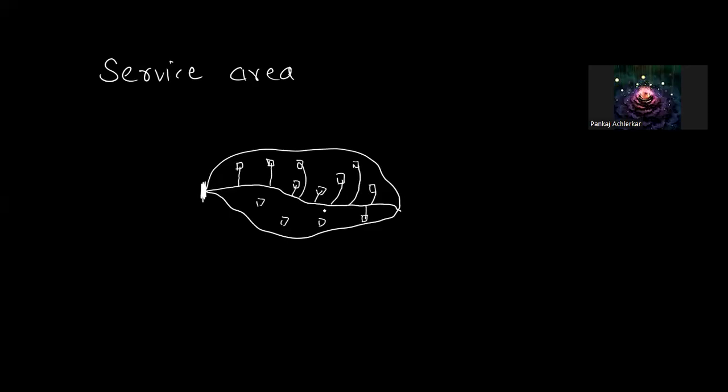So what are these laterals? Basically, these can be directly connected to the medium voltage level, the feeder voltage level, or there can be a secondary distribution system. For example, when I am representing this lateral, there can be a transformer which transforms the 11 kV to 400 volt, and 400 volt lines, which is basically the secondary distribution system to the individual loads which are present in this area. So let us say A in kilometer square is the cross sectional area occupied by that.